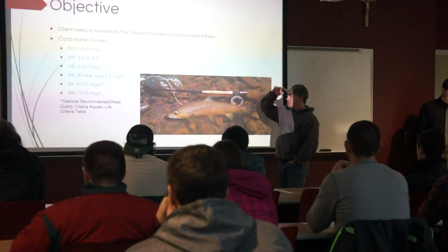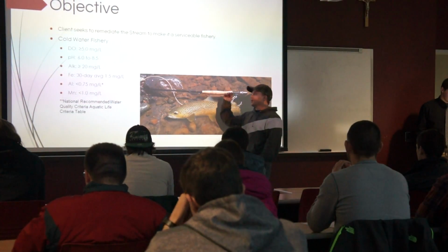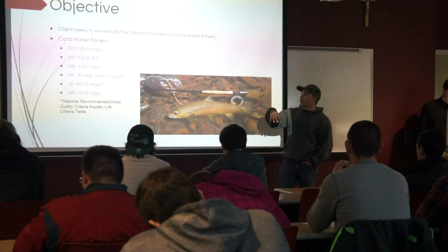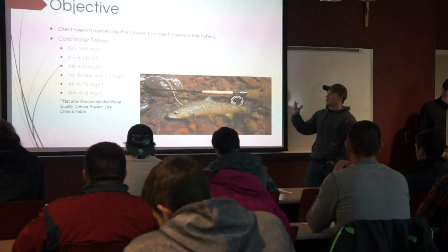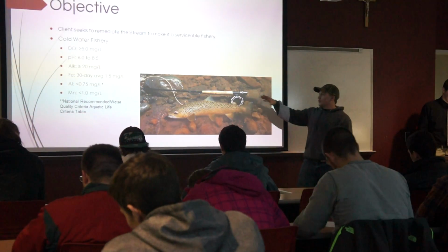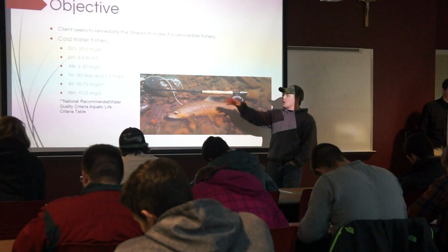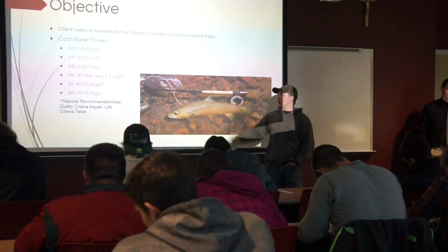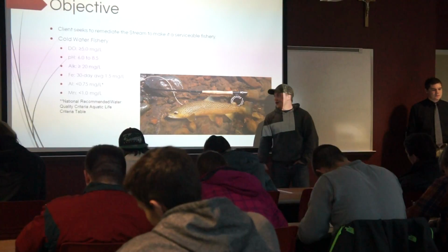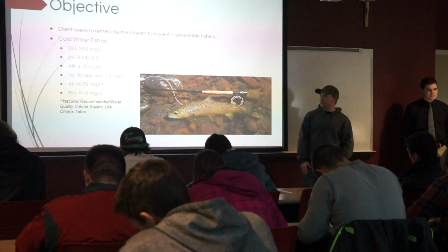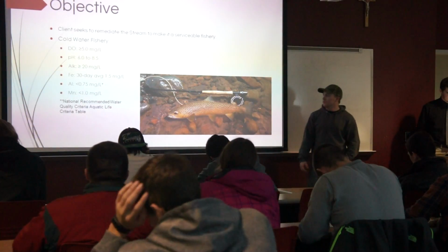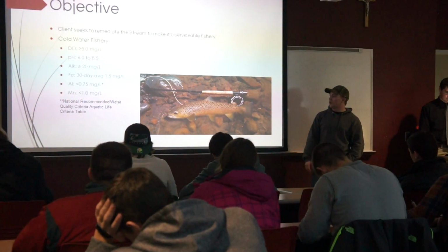So the objective for our project is to make trout run a cool water fishery. We want our alkalinity levels and pH to be within these ranges, and our metal loads to be roughly under 1 milligram per liter, which is the recommended level for cool water fisheries.